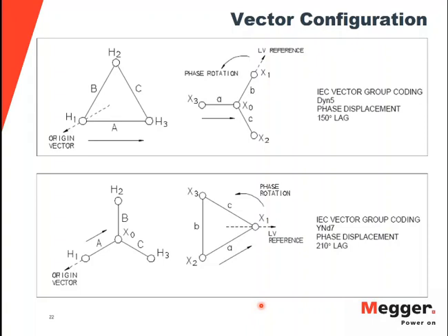Whereas a DLRO does not have any discharge circuit, which means that yes, you can run the test, you might get good resistance reading from the DLRO, but when you go and take the leads off, you might run into a safety concern where it has not been able to dissipate the energy.